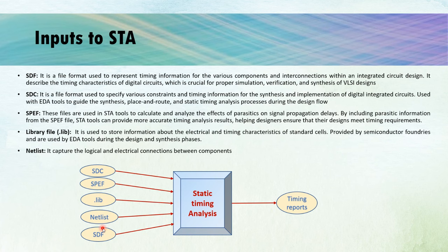So this RTL design serves as a bridge between the high-level system specification and the actual hardware implementation for digital circuit. As I've already discussed in my previous videos, before coding the design using HDL, we do top-level specification design and test it using a high-level language like C, C++, MATLAB. And once it is tested, we move to the HDL language like Verilog or VHDL for the design cycle for the digital design.